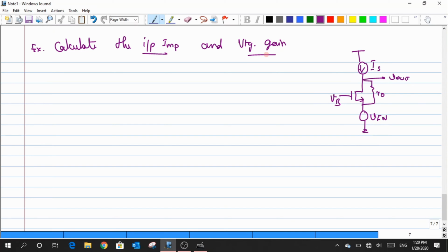So now what happens in that case? R naught was connected to our drain resistance, right? Right now the drain resistance is infinity. So R naught, when it gets added to it, it's again infinity, okay? If you could recollect, when I had a resistance RD here, we ended up having the value of Rin as something like R naught plus RD divided by this GM prime R naught, right? But what has happened is that the value of RD has now become infinity. What happens to the entire formula? Infinity. So infinity divided by anything is equal to infinity itself, right? So we have got the value of Rin equal to infinity.